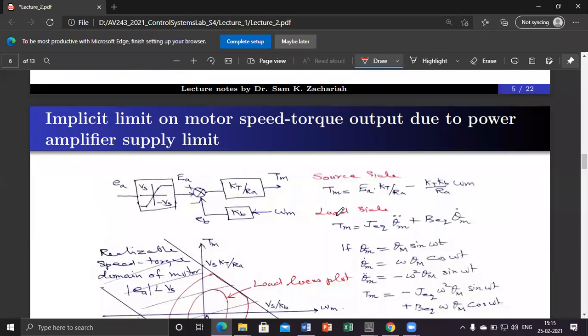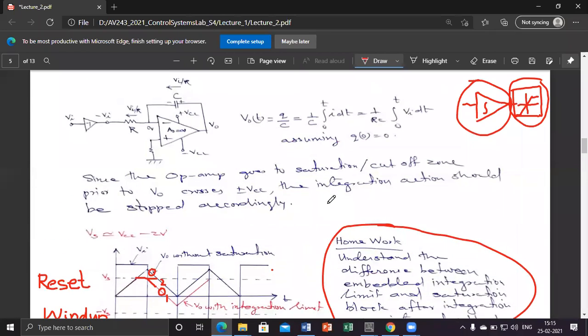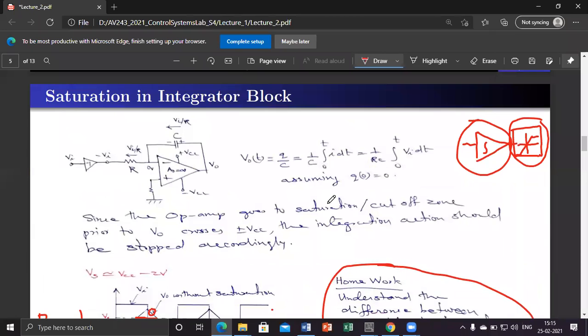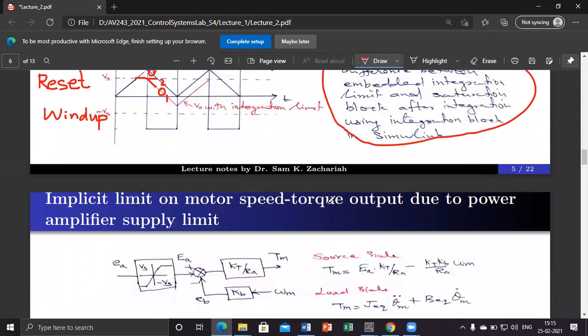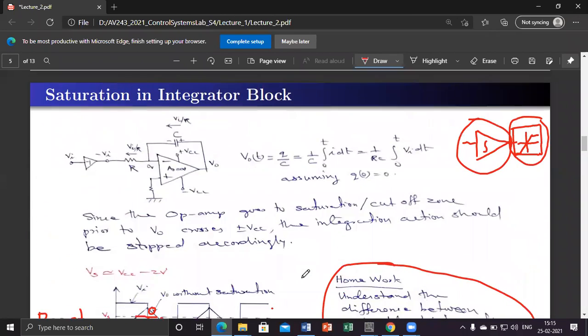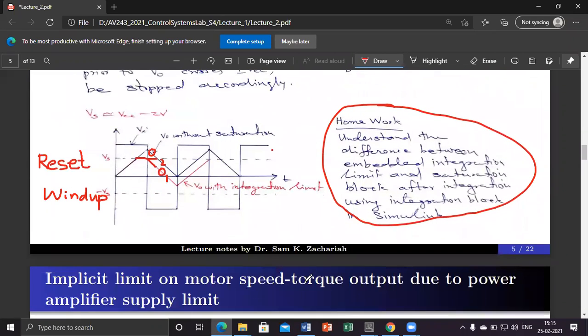Study all the features and exercise them, and you can apply those features in the PI controller implementation that you are going to study. And for the limit of the integrator, for example, in the same control loop, you can implement the integrator limit using the inbuilt integrator limit as well as an external integrator limit. Take the step response and see the difference. Then you can appreciate the benefit of using the inbuilt integrator limit. So this is a very important portion. Go through it, study it well.